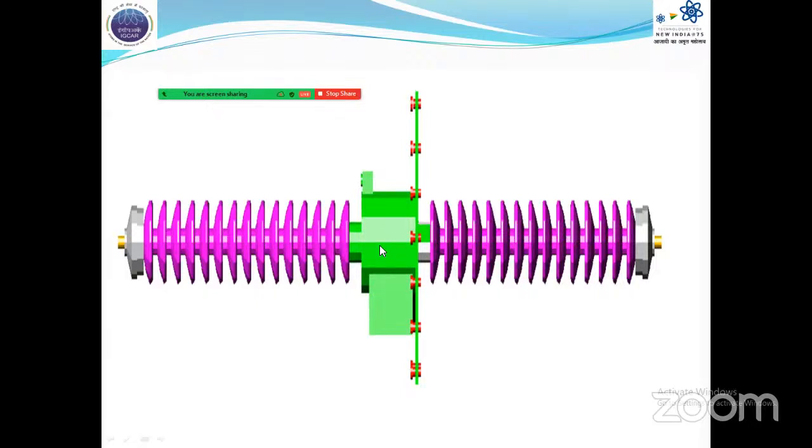The transformer protection CTs were located inside the transformer bushings in the old transformer. The failure reason for the old transformer was mainly due to the flashover that occurred in the CT turret of the old transformer bushing. So it was decided to take the transformer protection CTs out of the transformer bushings into wall bushings, so that any problem or flashover that occurs in the wall bushing will not affect the transformer. That is a major change we have made in this new wall bushing. So CTs are shifted here.